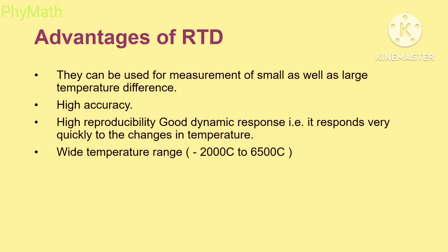Now the advantages of RTD. First, they can be used for the measurement of small as well as large temperature differences. Then next, high accuracy, then high reproducibility, then good dynamic response. Then next, wide temperature range, that is from minus 200 degrees Celsius to 650 degrees Celsius.